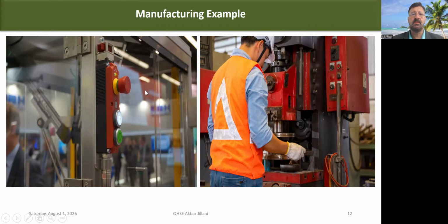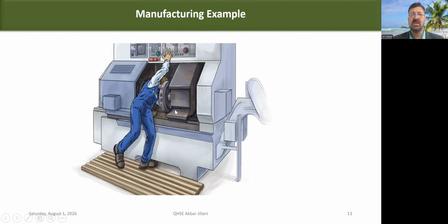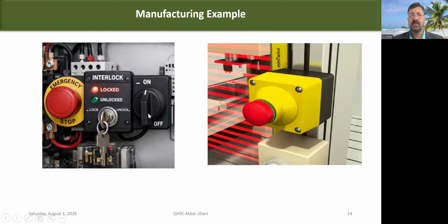Now here, these are the emergency stop buttons. These are the guards. Now here, also we can see sometimes we have this type of accident. Over here, the emergency button is not in this, it is here. So he didn't press it. Now these are the emergency buttons. Wherever you go, the emergency button will look like this. This is universal. Throughout the world, we have this.